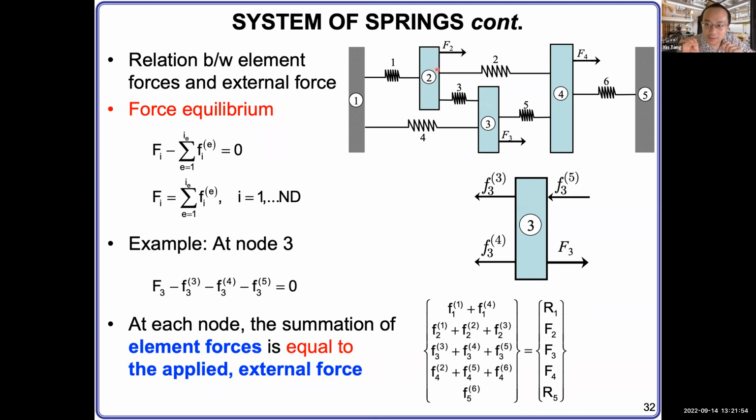These two forces are in inverse sign because they cancel each other. So by adding all the force generated by the spring together and then adding a minus sign to it, it actually gives the force applied by all the springs on this node. That force should be in balance with any external applied force.